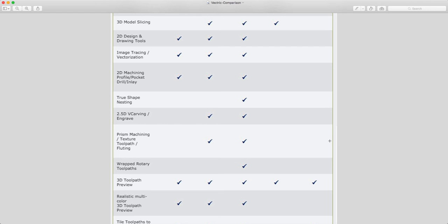Now this is common when you're using a V-shaped router bit and you're doing lettering for signs. The bit will actually engrave a V shape for each letter, and as it gets to the ends of the letters, the Z-axis will move up to thin out the letter, whereas in the wider parts of the letter, the V actually goes deeper, and it gives you that really nice three-dimensional V-carve sign look. That's a standard feature on both VCarve programs, but is not available on Cut2D.